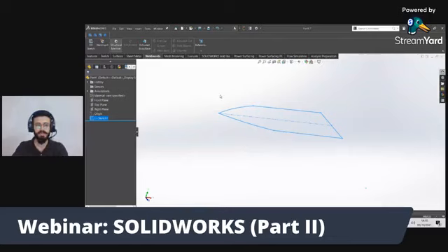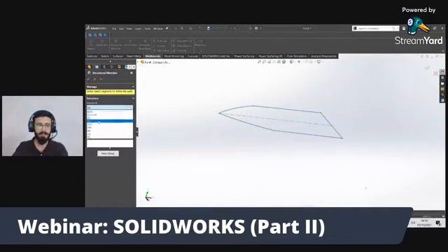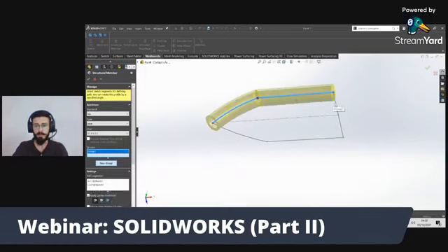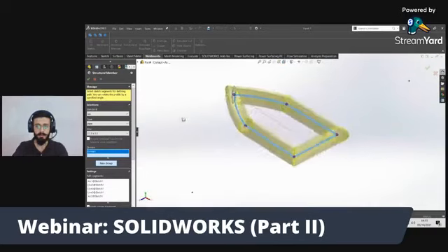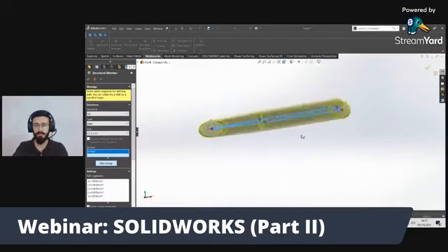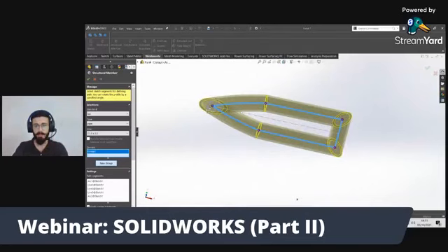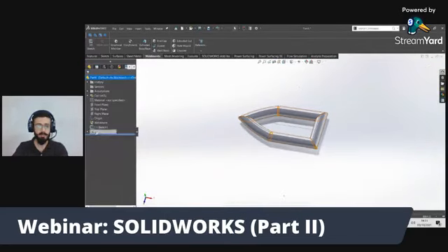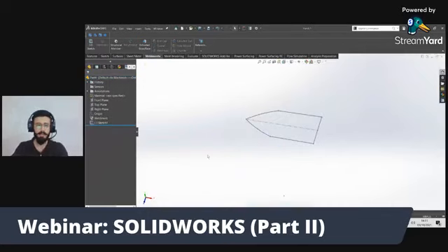Then we will go to weldment, structural member, and then we will select pipe. We want it to be a circular pipe. Then add a group, new group, and see, this is how it's done. And if I want to make a support here in the bottom, I can add this, I can add that also. Let's delete this weldment so we can design this through a single weldment.